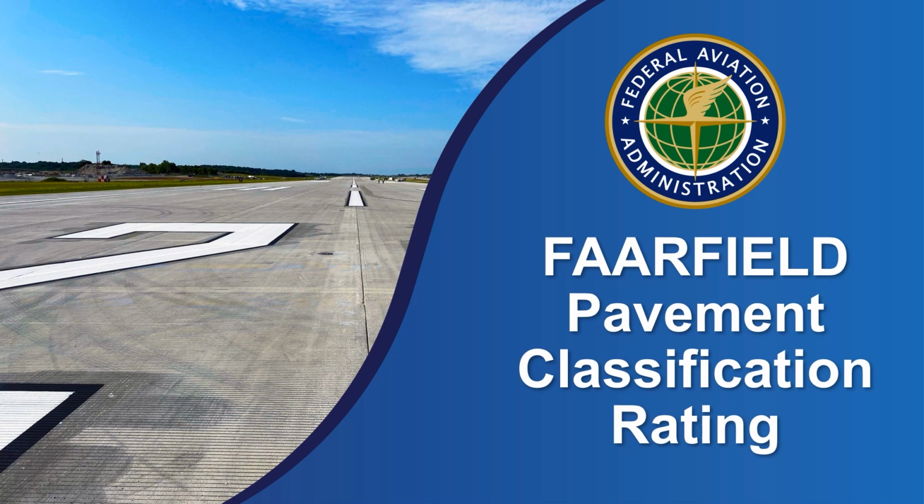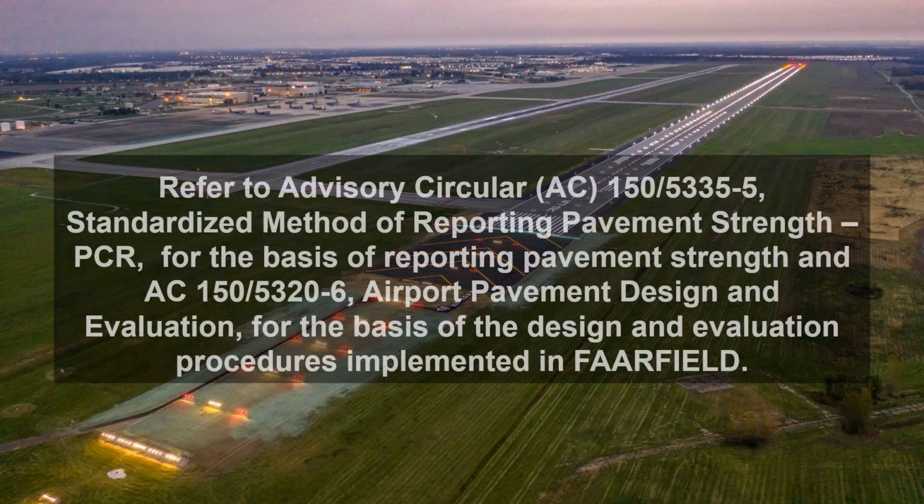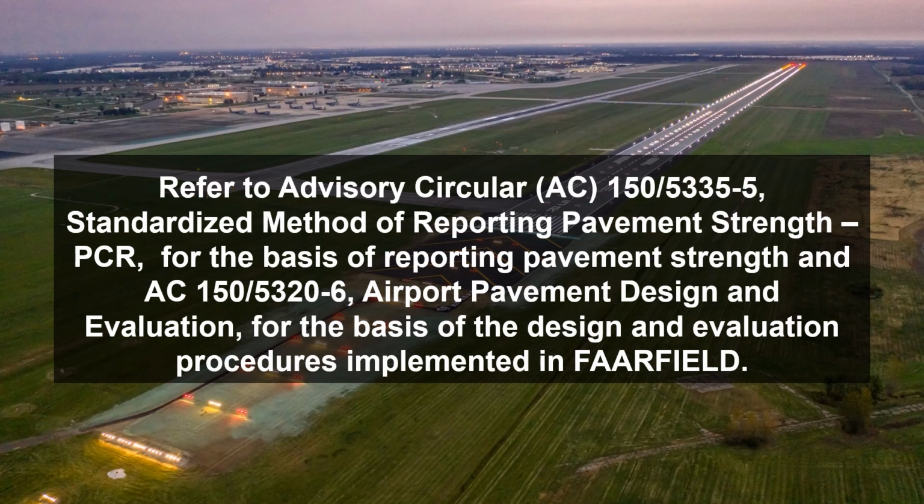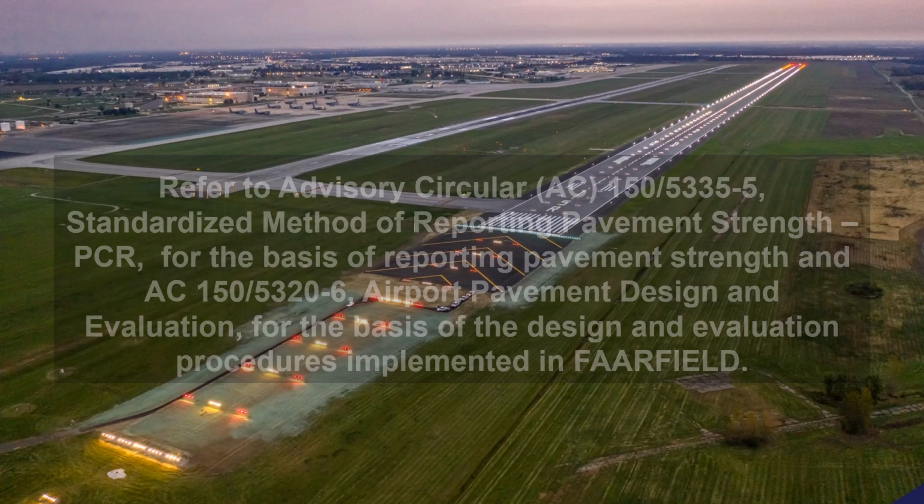Pavement Classification Rating. This video provides an overview on what PCRs are. We will demonstrate how to use FAARFIELD to model existing pavements and calculate PCRs. Refer to Advisory Circular AC 150/5335-5, Standardized Method of Reporting Pavement Strength, PCR, for the basis of reporting pavement strength, and AC 150/5320-6, Airport Pavement Design and Evaluation, for the basis of the design and evaluation procedures implemented in FAARFIELD.